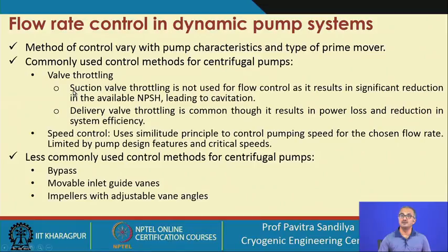Now, let us see whether we should throttle. Throttle means partially closing, not fully closing, so we are doing a bit of pinching. Whether we should throttle on the suction side or not, let us see. It is not recommended. Why? Because if we throttle the suction side, the NPSH will come down, and as we have learnt earlier, if NPSH comes down, there is a high probability of cavitation. So, generally it is not recommended to throttle the suction side valve.